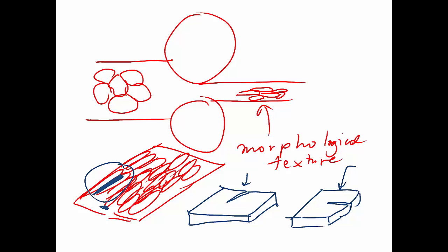Although this kind of argument is not really accurate, because fracture toughness in theory is supposed to be independent of the defect. It has more to do with how energy is absorbed as a crack propagates in this direction. And what you will see here is that the crack will propagate with very minor changes in path, while here a crack will probably have to follow a much more meandering direction. And maybe that's what is causing the difference.